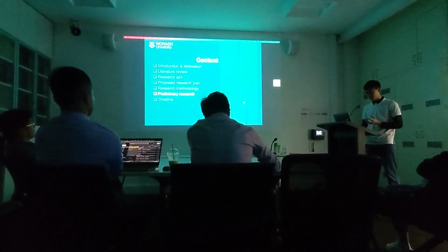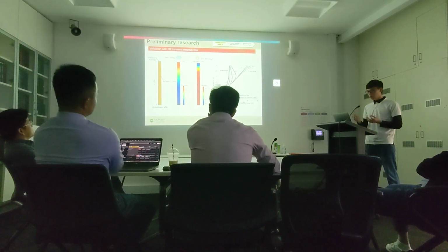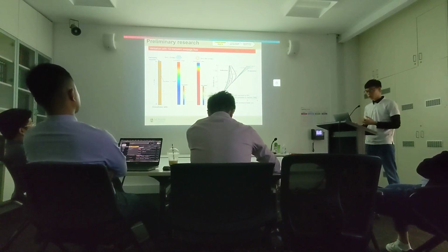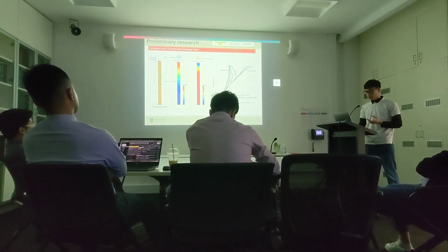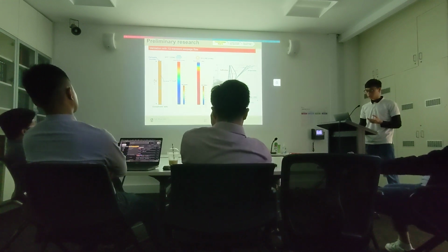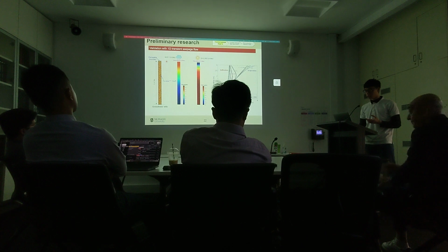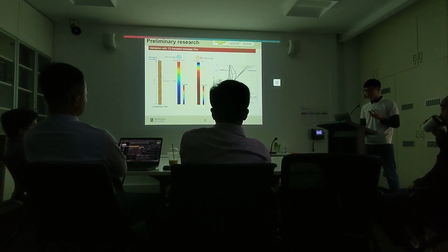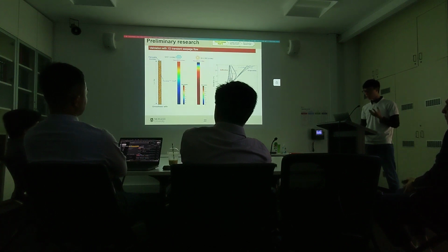Preliminary research. First, we validate with one-dimensional transient seepage flow. Here you will see the initial condition, this is the 3 meter soil column, the positive flux here represents rain, and the negative flux represents the opposite, which is infiltration or evaporation, and we compare with the analytical solution.